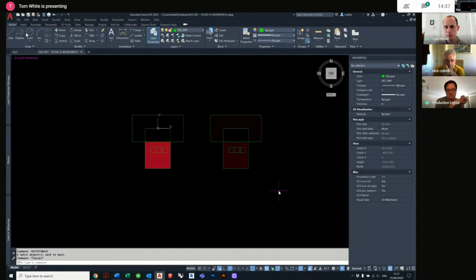More often than not, I'll get a drawing, someone says, I can't make a hatch work. And it really is as simple as the polyline hasn't been closed, and CAD won't do it. Yeah. Don, would you be so kind as to remind me of the next subject?